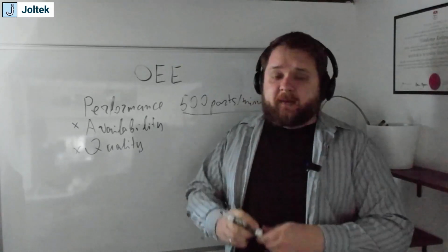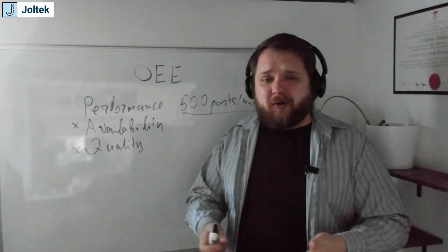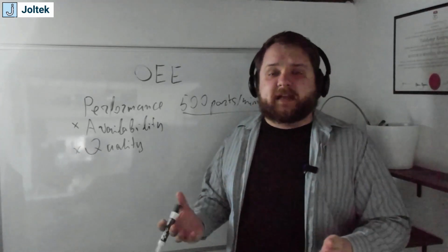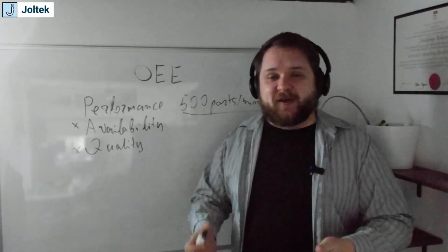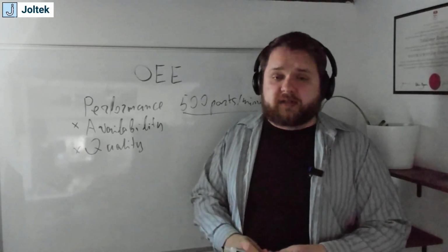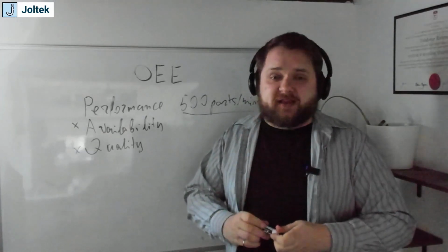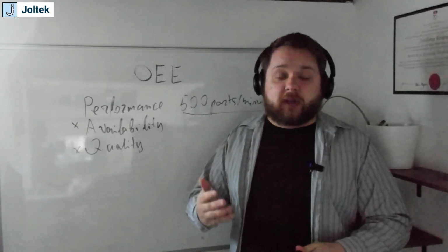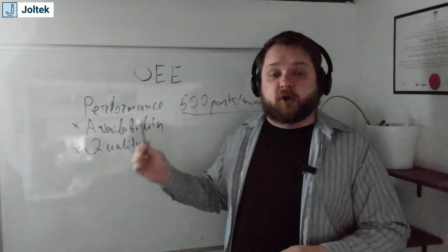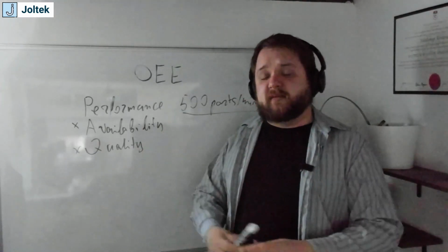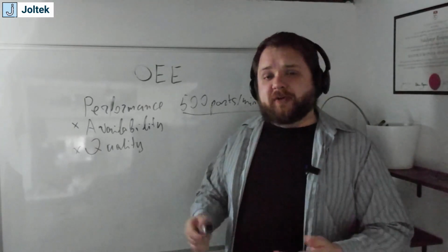When it comes to OE, you can be pulling data every 5 minutes. You can even store that data every hour, and usually there's not going to be a whole lot of need to be polling your PLCs or your control systems, your DCS, on a very narrow interval. And I see this mistake all the time. Again, if you're being sold a specific piece of machinery or maybe a solution that is going to be pulling that data into the cloud, you start seeing a toll on your networks. This is not going to be OE related. OE is going to be a fairly slow and steady metric that you want to collect, obviously with certain delays, but ultimately you don't need it every millisecond.